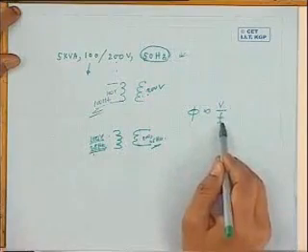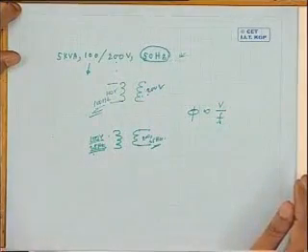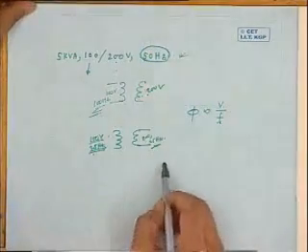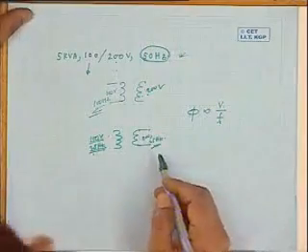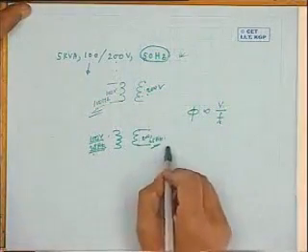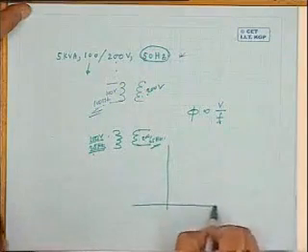Applied voltage I am keeping constant, the magnitude of the RMS voltage. If you reduce the frequency by half, the flux level will become double in the core. Now in a transformer, how much will be the magnetizing current? That becomes the crucial point.